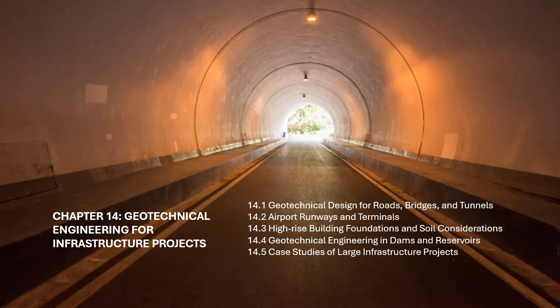Toe drains and filter systems. Toe drains are used to remove water that may accumulate at the base of the dam. These systems typically consist of perforated pipes or gravel-filled trenches that allow water to flow out of the dam while preventing the movement of soil particles. Filters are often used in conjunction with drains to ensure that fine materials do not clog the drainage system.